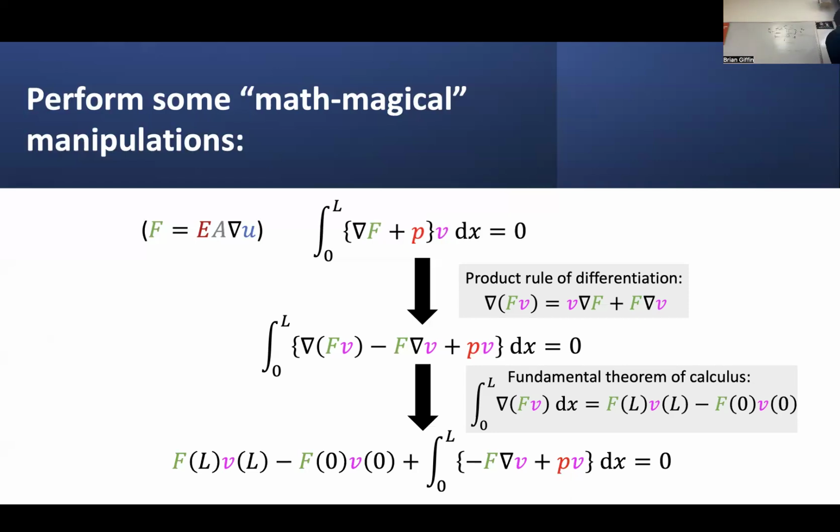Small manipulation, but you'll notice the important thing that we've gotten out of this two-step transformation is that the problem that I pointed out earlier, in having this expression involve a derivative of the internal force field, which required that the internal force field was differentiable, I've done a few manipulations and voila, look, now I don't actually have any derivatives with respect to F. Which means that if I wanted to evaluate this expression, which is entirely equivalent to this expression, I can do so without actually having to take any derivatives of F, meaning I don't necessarily require that the internal force field has to be a nice, smooth, and continuous function that has well-defined derivatives.